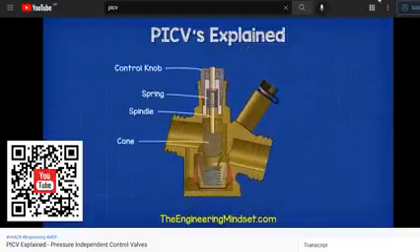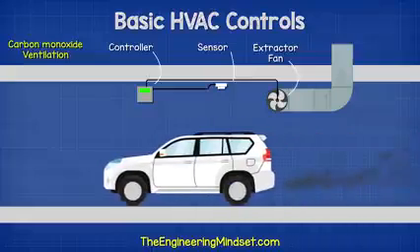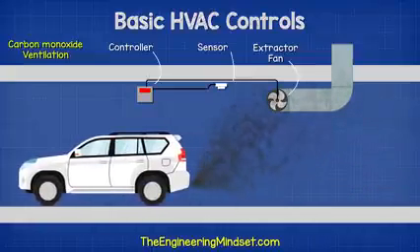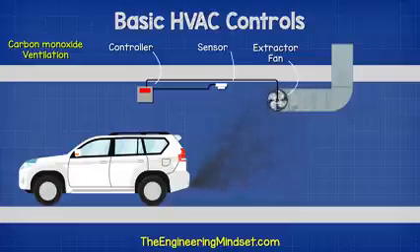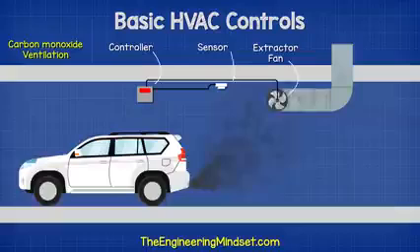We also need to regulate the quality of air. For example, in an underground car park, we might find a carbon dioxide sensor which controls the speed of the ventilation. Rather than running the fans constantly at high speed when they're not needed, the fans vary their speed to match the ventilation required, depending on how much carbon dioxide is in the air.